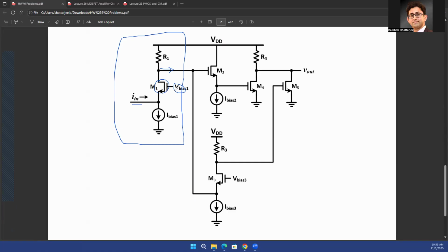Right? So you already know the components in this big circuit. So do a divide and conquer, find out what are the known components. For example, this component is a common gate amplifier. And for that common gate amplifier, one interesting thing that you need to keep in mind about the gain is that the gain is plus GM times RO, or GM times, let's say, R out, whatever R out you have. Now GM is the GM for this transistor. R out is the output resistance that you see at the output node, which is over here.